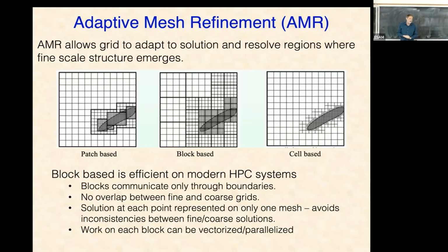Again, for load balancing issues, if you take smaller time steps, then each block has a different amount of work, and moreover, communicating the boundaries at different time levels gets much more complicated. There are accuracy issues in terms of doing temporal averaging of the fluxes between neighboring levels. And the loss of efficiency of having different time steps sort of makes up for the extra work you have to do by having a uniform time step everywhere. So in our experience, unless you have very, very deep AMR grids that go for 20 or 30 levels of refinement, then doing this single time stepping seems to be okay.